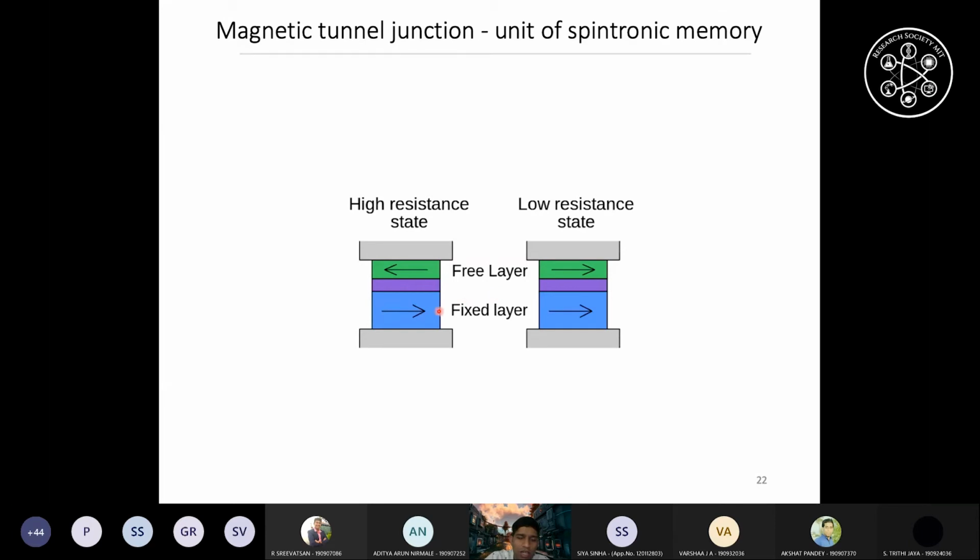So what is the advantage of the insulator? These guys saw that the difference of the resistance can be very high. It can even go to 200%. If you put copper and so on, those guys saw a difference of only 10 to 20%. That was enough to get a Nobel Prize, but not enough to use in a magnetic memory. If you put MgO, the electrons can tunnel from one direction to another, and the difference of resistance will be very high. And a higher difference of resistance means it is easier to read, right?